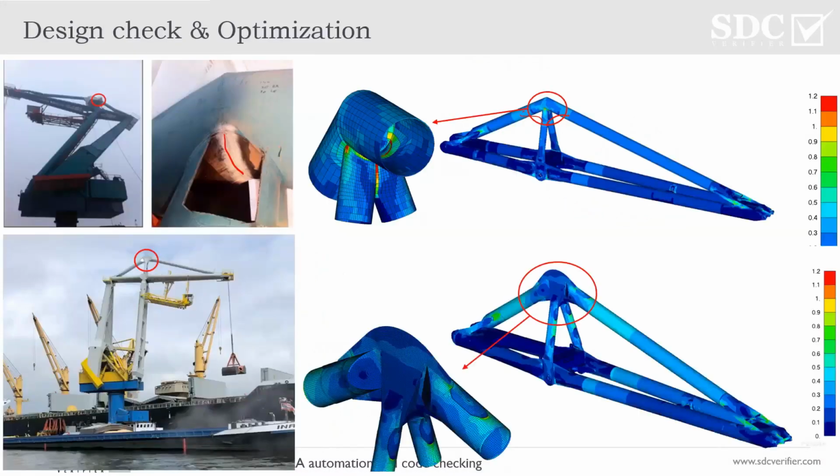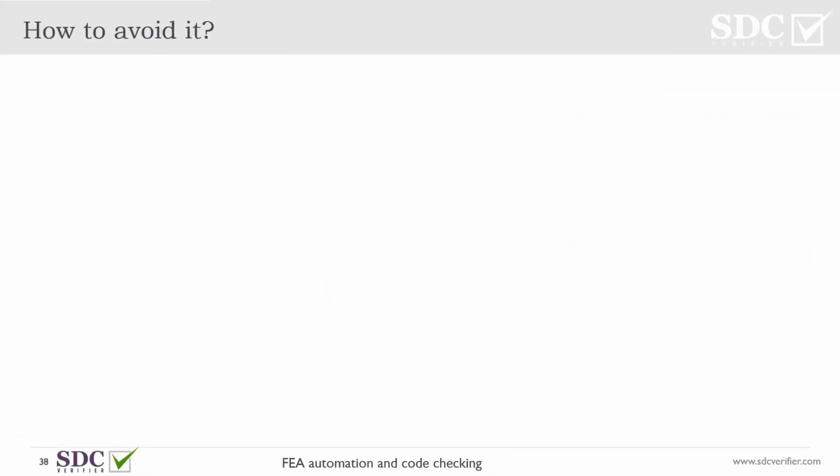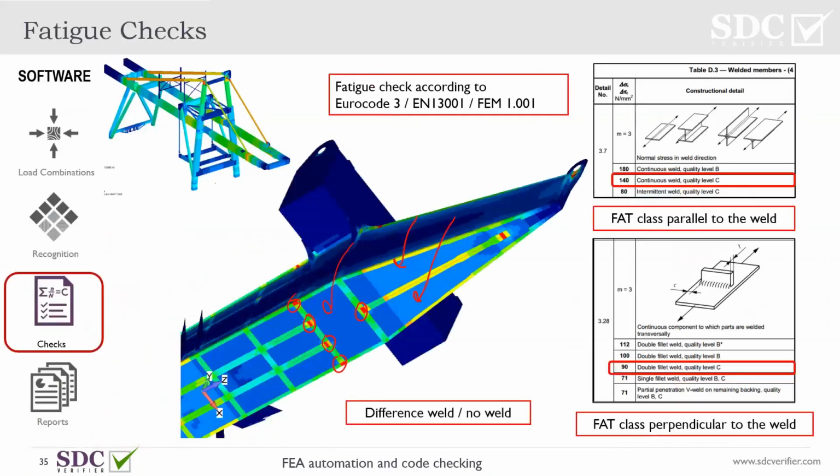Okay, that's a good question. Depending on the quality and the current state of your welds, the standard prescribes in general several different levels. So this is C, B, and D. If you have a really poor quality, you can end up with D, for example, but in most cases, weld quality C is a good assumption for detailed verification. But keep in mind that you need to take into account different types of your connections besides the weld quality.